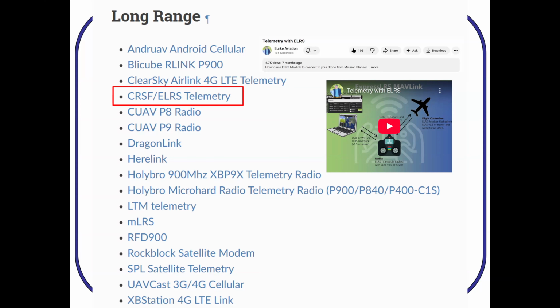So I'm going to propose and encourage you to use a radio that you've already put on there. And all you have to do is change the firmware. You're going to moan when I say that because you've done so much firmware change. So you can moan, Professor Berg, more firmware. But what you get is no hardware, and you get long-range telemetry to your drone, which goes as long as the ELRS, which is tens of kilometers. And it's no hardware. So I'll walk you through that also in today's lecture, and we'll do a demo.